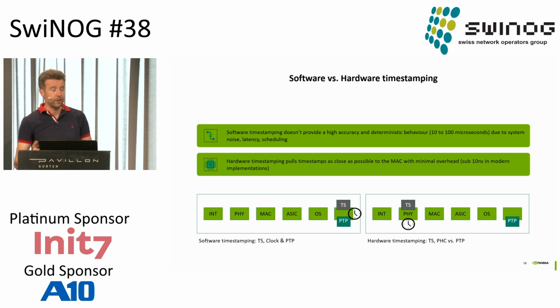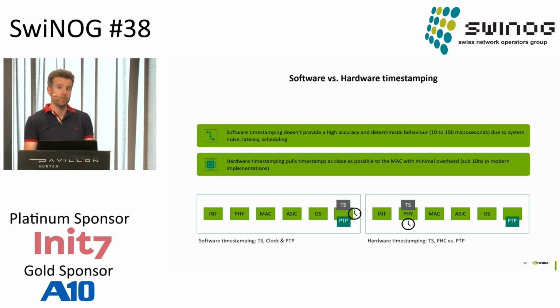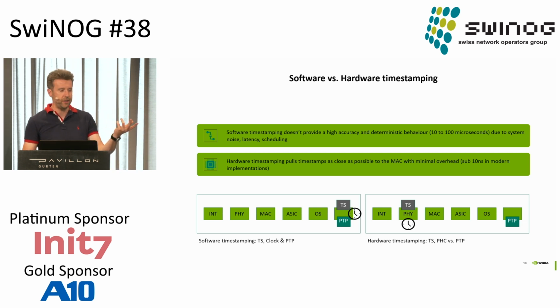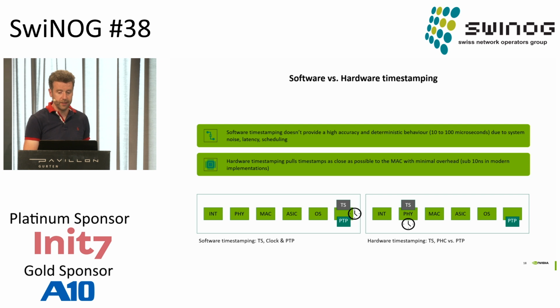As opposed to the right side of the slide where we talk about hardware timestamping, and here we want to pull all the timestamps as close as possible to the physical layer, okay? Which means that in modern implementations, you can get sub 10 nanoseconds for no extra cost, depending on the type of hardware you're getting. If you're getting a home grade 50 Swiss franc NIC, you might not be achieving that. If you're getting something that's more data center class driven, you most likely will. So as you can see, the timestamping now occurs more at the PHY layer, and then it is read from there, and then it will go to the PTP stack sitting at the top layer, of course.